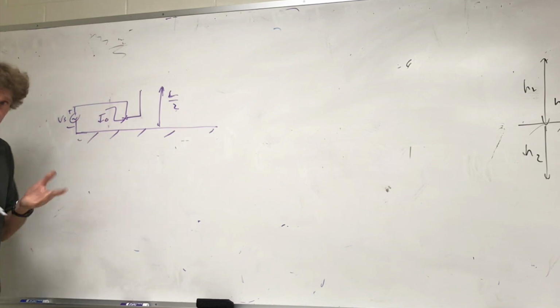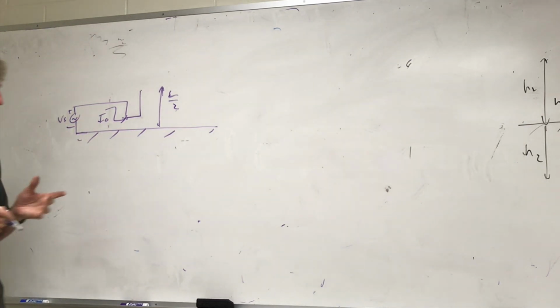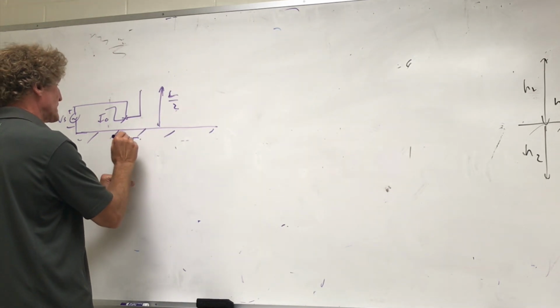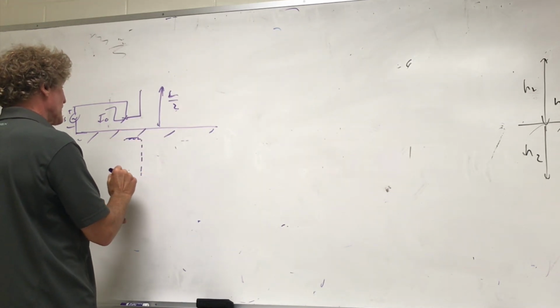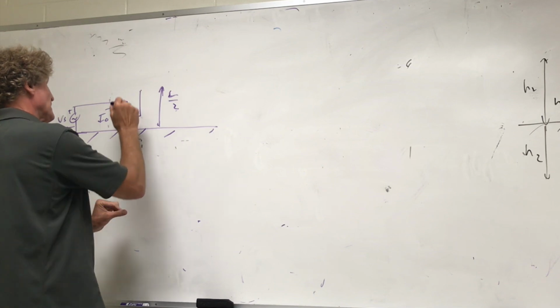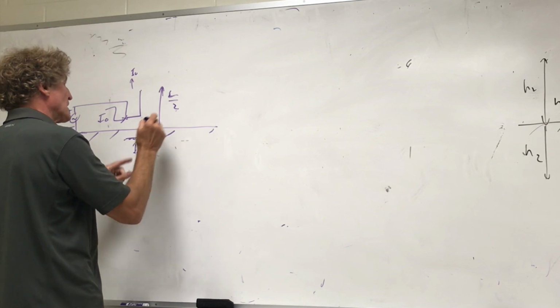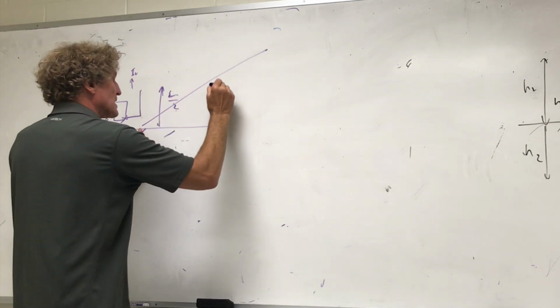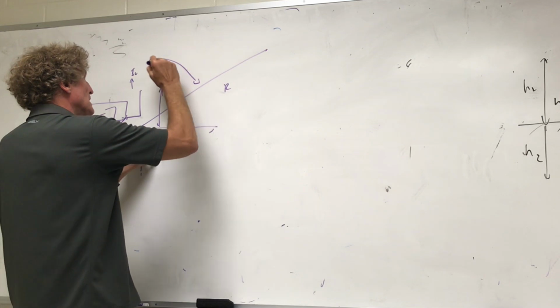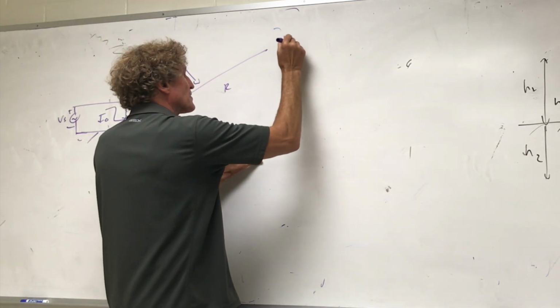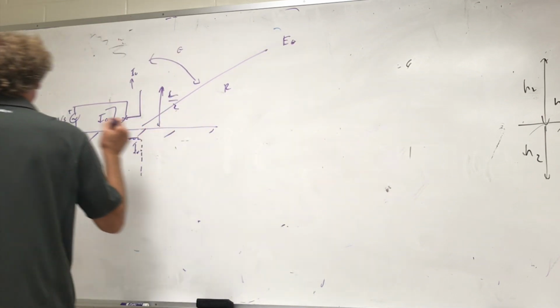Right? With me? Remember, there's an image right here, with the same length and the same exact current, in this direction, and we give rise, as a function of R and theta, to an identical electric field E out here for the short monopole. This is a short monopole.